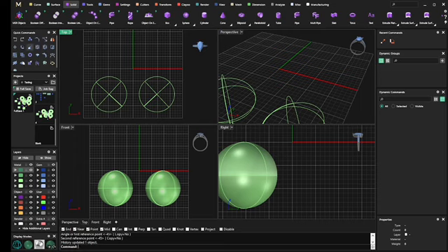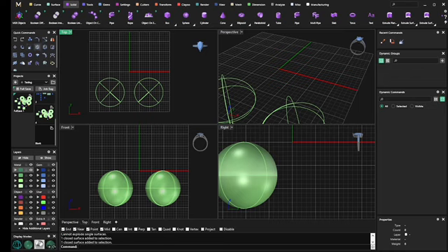Okay, so now we are going to explode. I don't know if it will allow me to explode the sphere, but let's try it. I clicked explode. Please select the objects to explode. I'm going to select this one object. Press enter when done. All right. It says it cannot explode single surfaces. So the sphere is considered a single surface evidently, and it will not explode that. Okay. I didn't think it would.